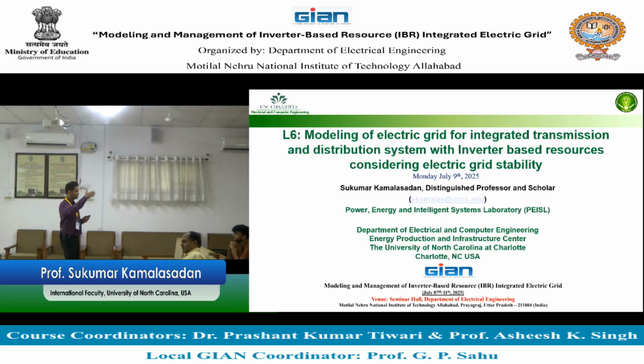So you know what voltages are. You can actually see what are the losses in the system. You can see how the power goes from the generator to the load. In the distribution system, you are more interested in losses and more interested in voltage. In the transmission system, you are more interested in generator scheduling, how many generators are connected and how do you schedule the generator to supply power, those kinds of things, right? So we know how to run a model of electric grid through power flow.